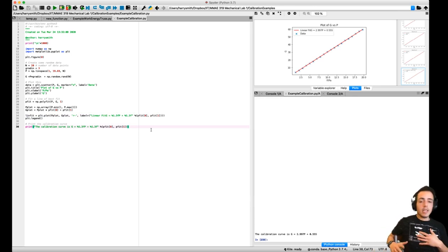Now, the calibration coefficient is not this thing here. It's 1 over this part that we have. We've got to be careful about this zero offset here. We need to make sure we record it. We don't necessarily use it during our experiment. We just have to make sure that we're aware of what this value is and check if what we count as 0 during our experiment is too far from this or not. So we can then just also print our calibration coefficients.